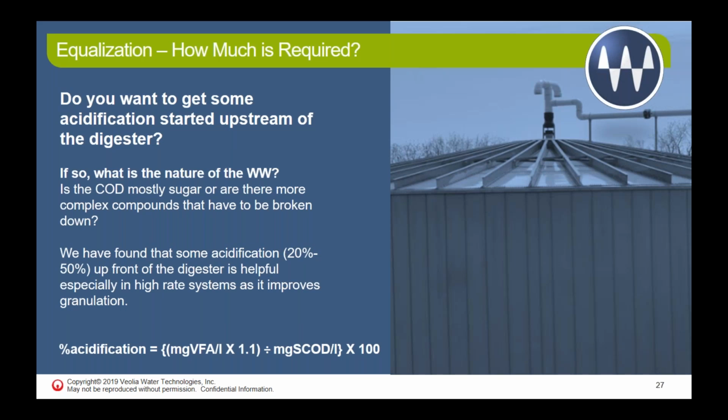But we also want to equalize the load to the system, because not all streams coming down will have a similar COD. COD is the organic load to the system. So we want to make sure we provide enough dampening, volumetric dampening, not just to equalize the volumetric flows, but also equalize the flows from the organic perspective.